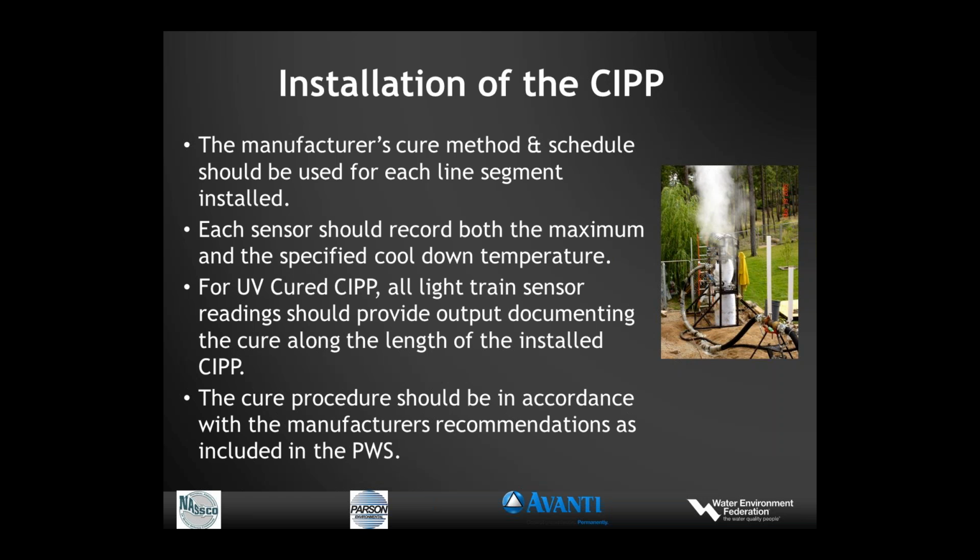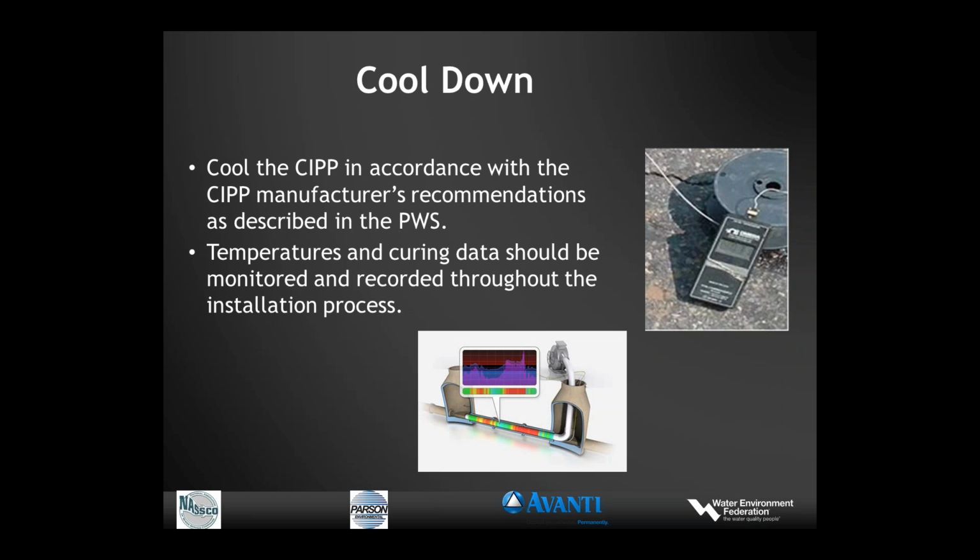The photograph shows a medium-sized cured-in-place pipe inverted by air, and it currently is being cured by steam. You can see the water vapor trailing out of the top of the tube. Cool down, of course, cool down should be in accordance with the manufacturer's recommendations.